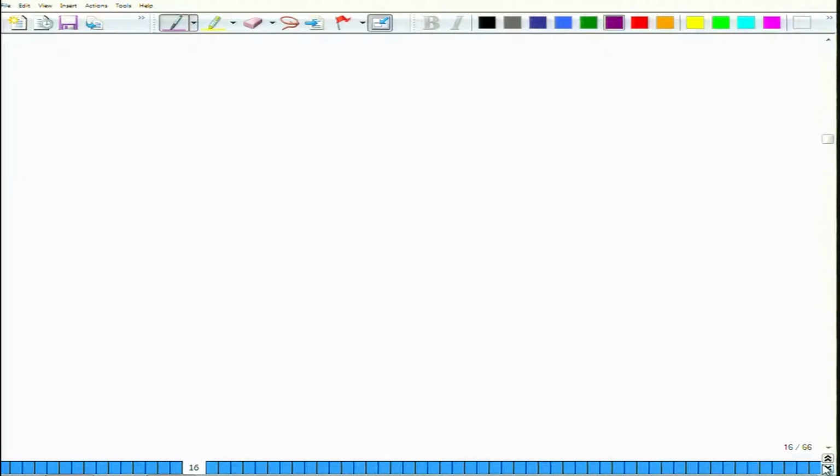So, you can determine the composition of the alloy. If you know the composition of the alloy and temperature, you can determine the composition of phases and their phase fractions. Let us first look at examples of common eutectic phase diagrams and common phase diagrams that are present in alloy systems.